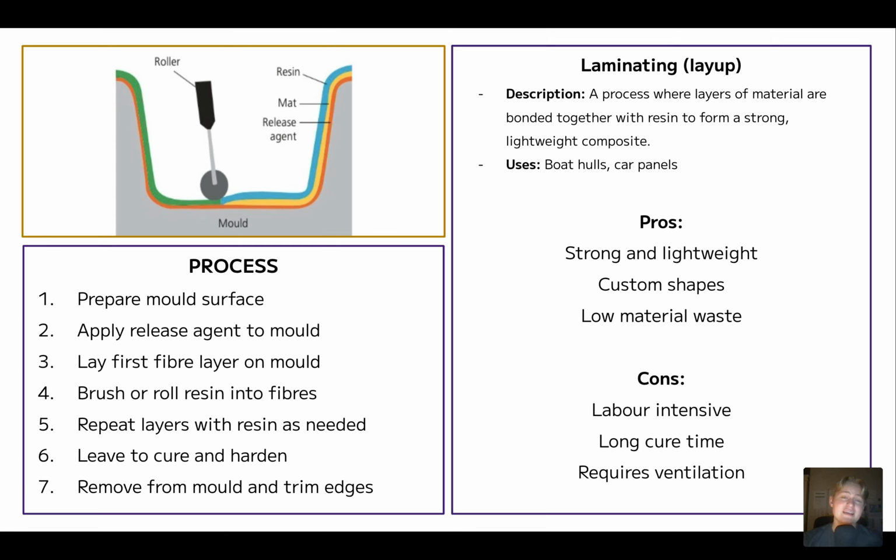The cons of it is that it's very labor intensive. I know, because I've done it myself and it takes a lot of time. And there's also a lot of time to wait around after you've done the process, because it just has to cure in the open. You can't put it in an oven or anything like that. It also requires ventilation, because obviously, resin, once it's hardening, heats up, and might create fumes, depending on what kind of resin you're using.